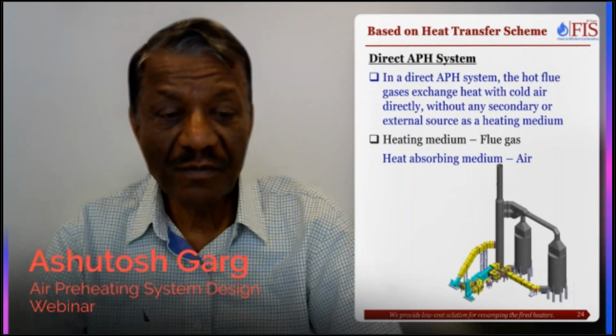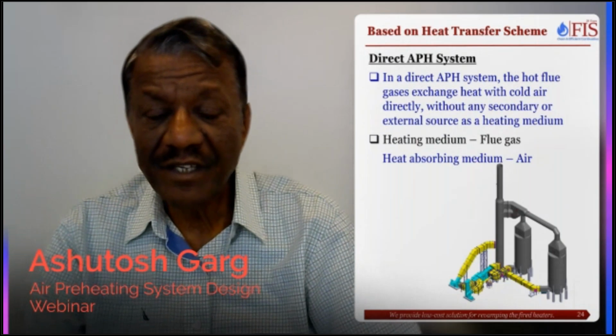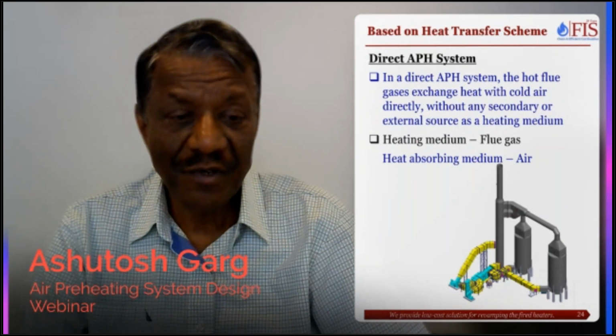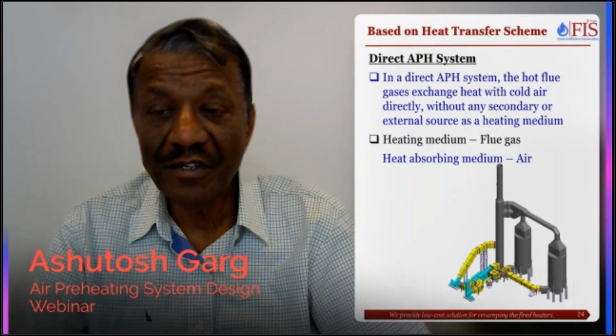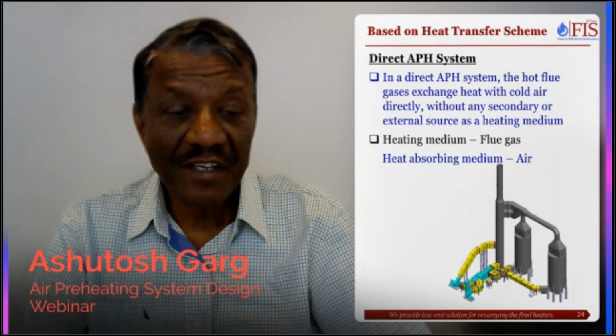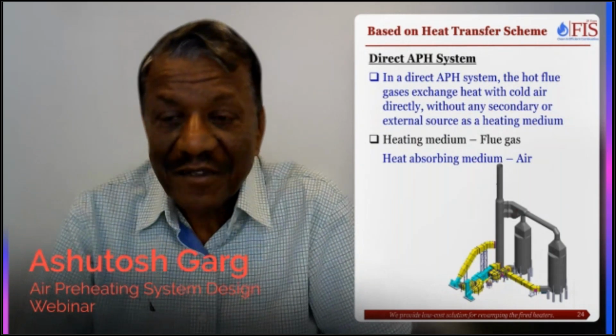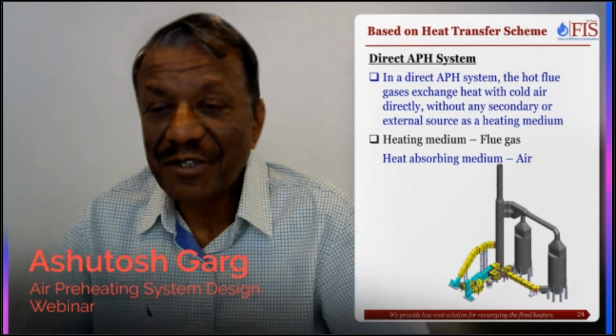And in order to minimize the duct, we installed this air preheater in an inclined fashion. One of the first air preheaters to be installed at an angle actually, and it's been working perfectly fine for about 15 years. Installed it against the manufacturer's recommendation, but it works.